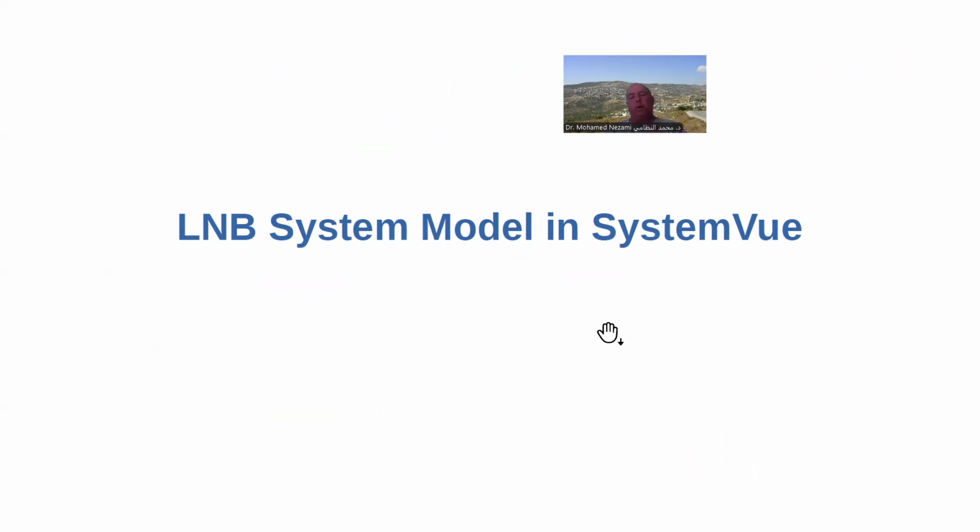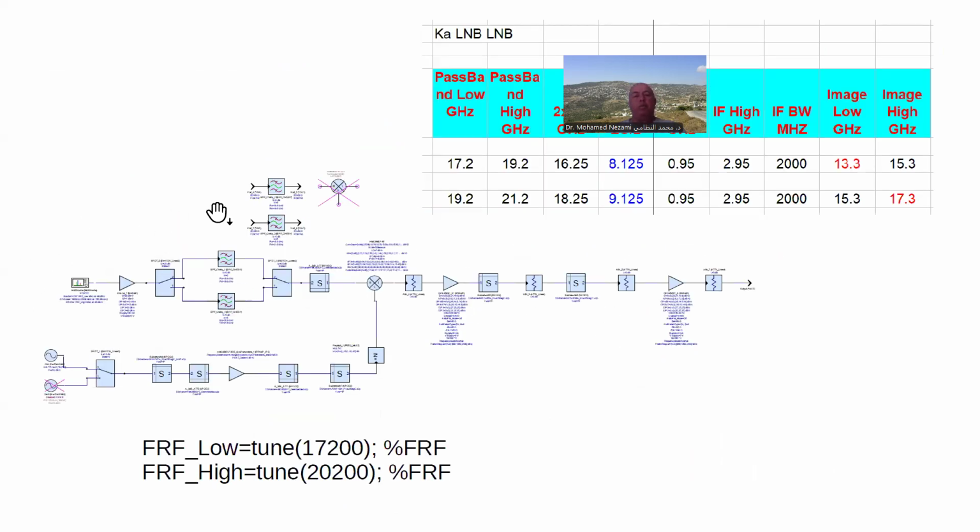So I picked all the parts, and then I constructed the system in here, as you can see on system view. Starting out, this is my SATCOM signal as a CW for right now, just like we would do on the bench testing one of these in actuality. And then, of course, your LNA section is still to be designed, but I have figured out the specifications for this LNA.